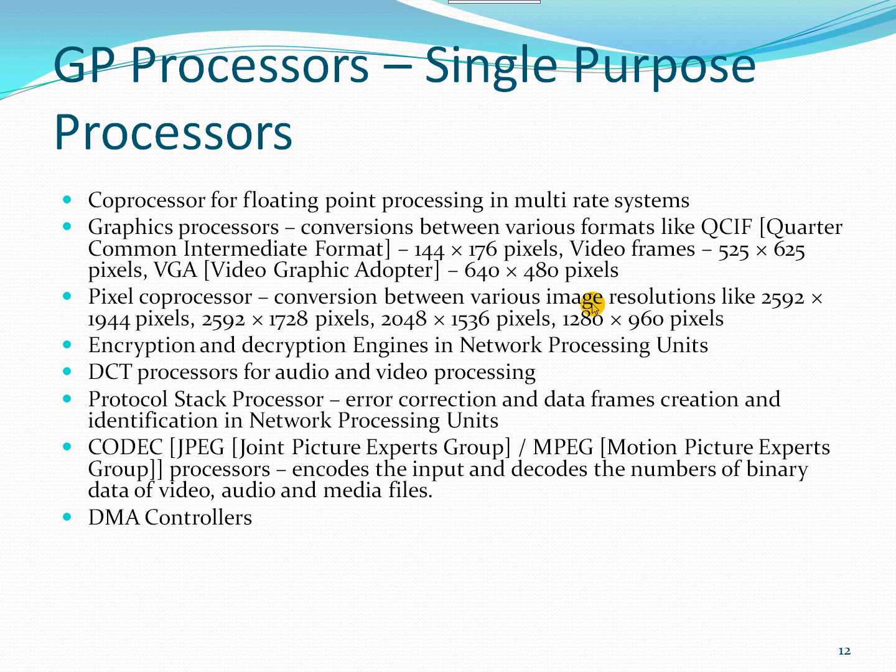But whenever we are going for embedded systems like camcorders and digicams, we need to have separate DCT processors so that the load on the main DSP processor or GPP processor is independent and those particular processes won't be getting overloaded.